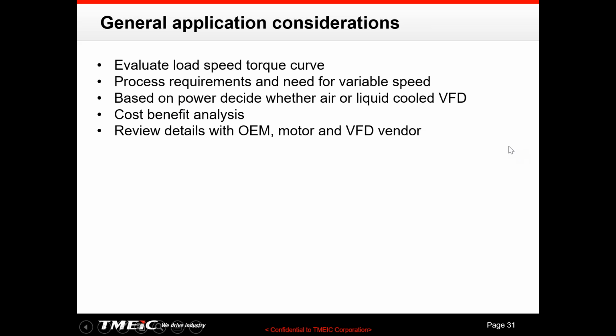So when we design the VFD, of course we need to know the requirements. Do you really need a full-time VFD, or do you only need the VFD for starting? What's the load speed-torque curve, and what's the speed range requirement? Do you need variable speed, variable torque, or constant torque?